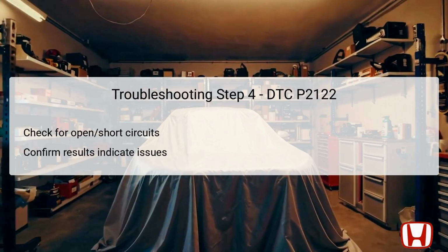Furthermore, check for APS1 being shorted to ground. Acceptable readings should exceed 1 megaohm, 1 MΩ. These results lay the groundwork for identifying whether the fault resides in wiring issues or component failures. Meticulous attention to these tests can save time and prevent unnecessary replacement of components that are functioning as intended.